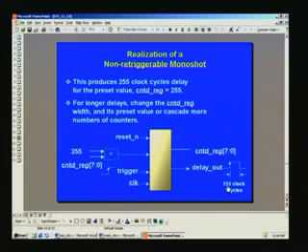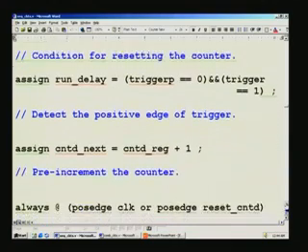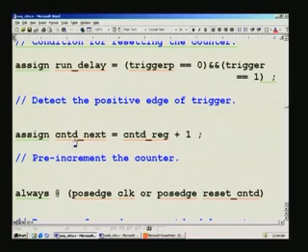And now you might have noticed this is the change I have made here, right. So also here, and that's precisely what is written here. For run delay, we sense the rising edge here, and as usual we pre-increment the register that here, and earlier I had used just C and T, I have renamed it as D, right, to indicate it is a delay that we really want to do. So I have just renamed, because otherwise that earlier counter will be overwritten by this, or this will be overwritten by the other one. So we can't predict that.